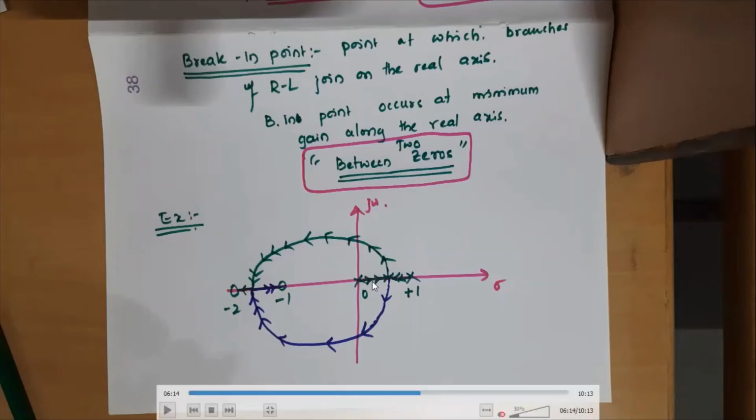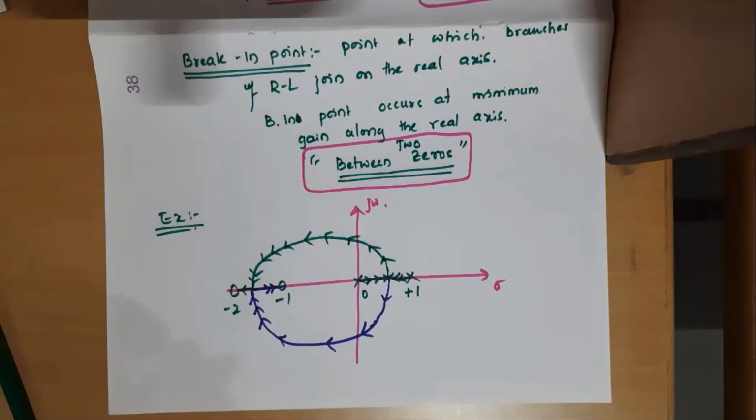Everyone please understand, the position of poles at 0 and +1 alone will not decide the stability. K will also be responsible for stability. Since K exists, these poles are shifting their position. Fine. So please understand that point. So this is conditionally stable.